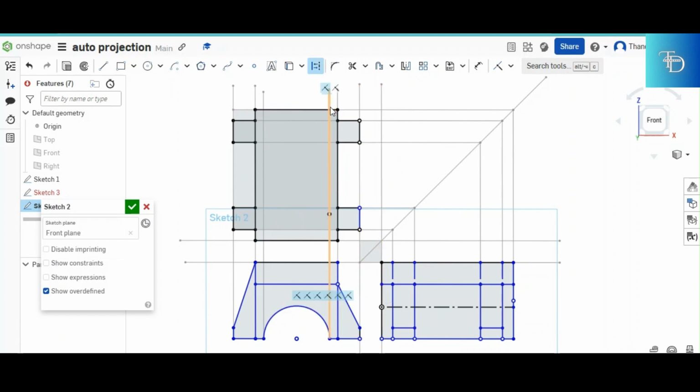The hole is inside the component when you are looking at it from the top view. Where does the hole start? It starts from there. It ends where? It ends there. So this point was projected, it is there. But how far does it go? There is the hidden detail for the hole. It goes all the way through. The same thing applies for the other side of the semicircular hole. It goes all the way through.